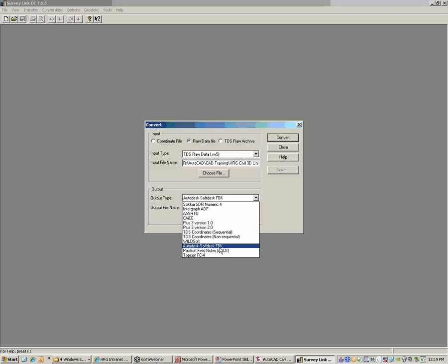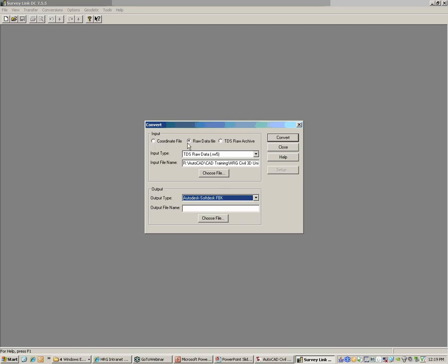I know Donnie was looking up at Survey and came to the conclusion that we don't really use RW5s that much, but I just want to mention that because I don't know if other offices are using RW5s or want to use those and have the line work. Really, Civil 3D is made to use RW5s. But if you're not traversing around and you're collecting everything with GPS, then you don't get an RW5 either way. So just wanted to clear that up.